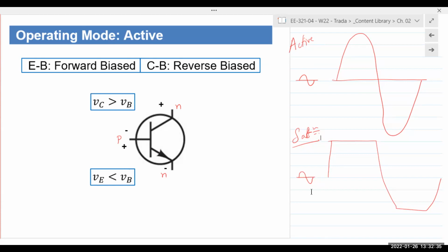So the DC voltage we're applying is, let's say, plus minus 10 volts, right? But now because of saturation mode, this output goes to like 25. Well, the transistor cannot supply more than 10 volts because that is what we're giving as DC voltage, as the biasing voltage. So it gets cut off and it's distorted.